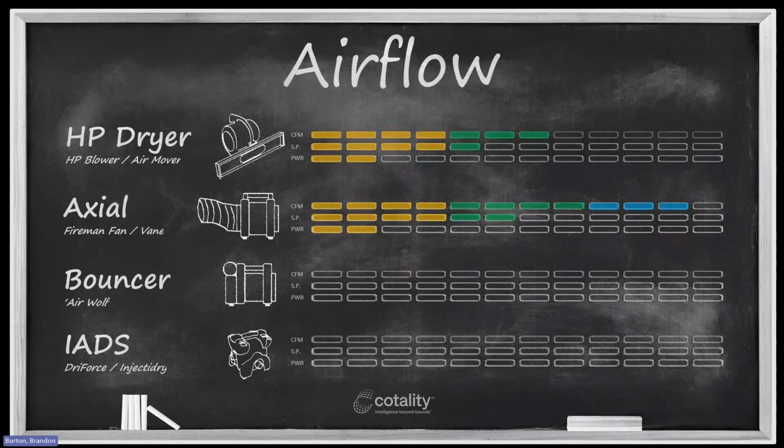depending on the design. And the reason for both of those being exceptionally high is what this is designed to do. What it's intended for is a safety fan. It's designed to take a really high volume of air and evacuate that air from a confined or contaminated or otherwise compromised space and replenish that with fresh, breathable atmosphere at 10, 11, 12, 13, 14 air changes per hour, whether that's after a fire, and we're trying to evacuate all of the carcinogens and the irritants that are inside of a space and evacuate all of that from the air and replace it with breathable atmosphere.